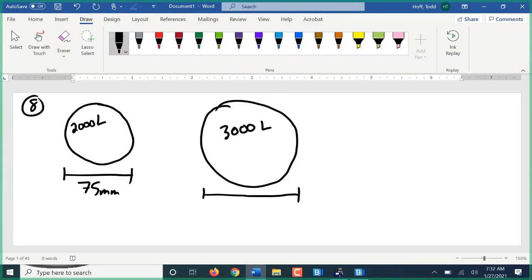First thing we have to do on this type of problem is figure out, is this a ratio of areas or a ratio of volumes? And at first glance, in this one, it looks like a ratio of volumes, because liters are capacity, which is related to volume. Unfortunately, we can't change the volume here. All we're changing, when we change the diameter of the pipe, is the cross-sectional area of the pipe. We're only changing it in 2 directions. We're not changing that 3rd direction.